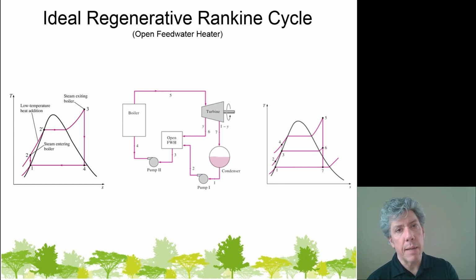And what are we going to do at that point? Well, we have to have a tap on the side of the turbine where maybe the steam has gone through a few sets of blades, but now we allow some of that steam to bleed off. It's called bleed steam. So you bleed the turbine. Now, a fraction of the steam is allowed to exit the turbine at this point at an intermediate pressure and not complete the journey through the turbine, expanding all the way. The rest of the steam, though, does move from state 6 to state 7. So there's a split at state 6, okay?